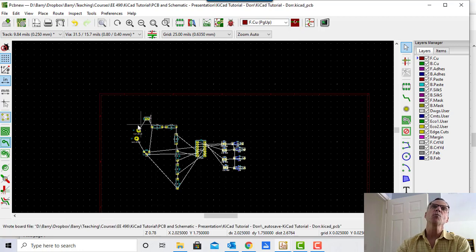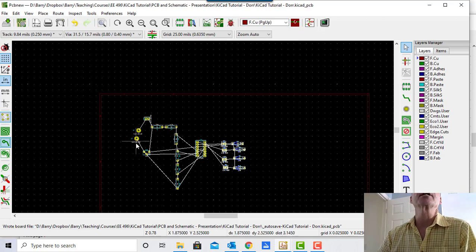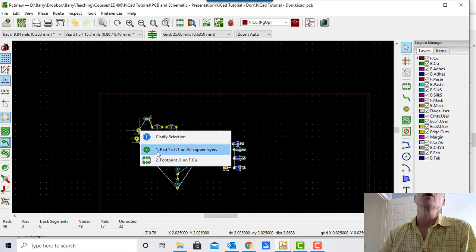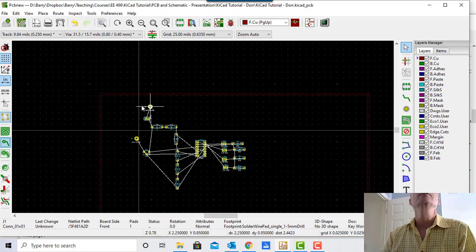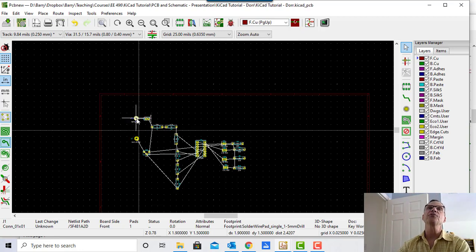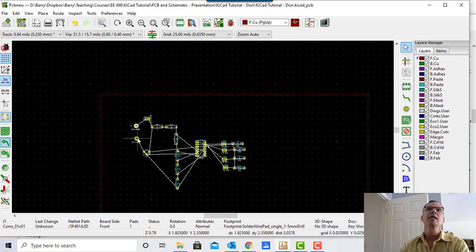So you can see that what I've done here is I've made our PC board look kind of like the schematic. Here are our wire pads where our plus and minus are going to come in. I can click it and I can move it. I know that this is going to be my positive one because I see the rat's nest line going into my little jumper. So I know it's in about the right place. And the other one, I can see the ground going to a bunch of different places. So it's pretty clear that this is the negative. So I'll throw it here.